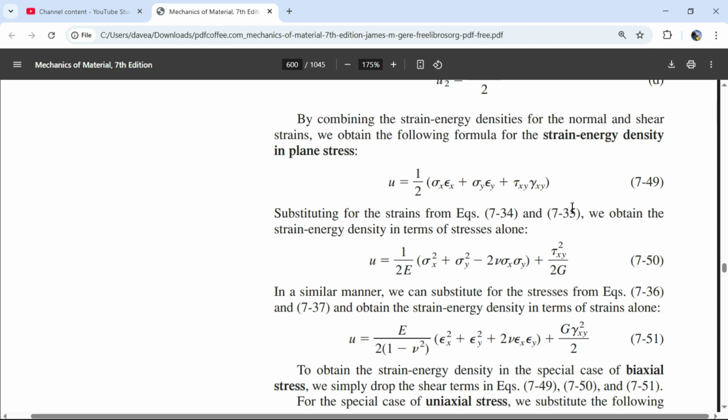And so that constant must be a pretty decent number, 10 million, 11 million, where the shear stress has to be somewhere in like the 30,000 range. 30,000 is equal to 11 million times 0.004. I just remember that if steel is 0.002, I can assure you from geometry this is 0.004. If they're saying strain in steel is 0.002, the angle that forms in shear, the shear strain, is an angle of 0.004 radians, just kind of multiplied by 2. So it's a good way to remember that.